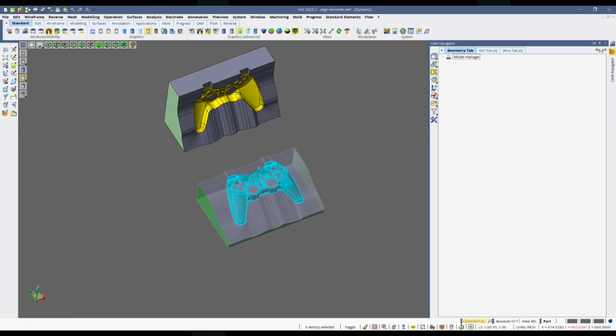The other option, if you have two separate piece models, then when you go to select geometry in 2025.2, it'll have you pick which piece model you want to use. If you hold control and select both of them, it'll automatically try to unite them. It'll open up the window to unite them and then put them as one single group.